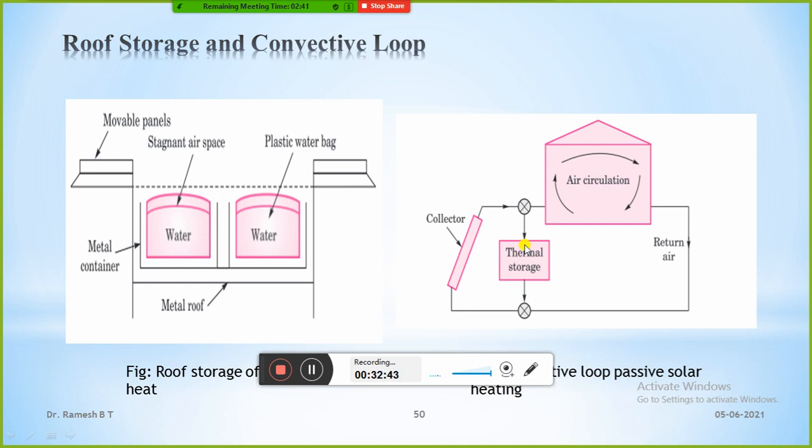If more solar heat is available than is required for space heating, the floor vent may be partly closed, and this heated air then flows through the bed, where it deposits heat, meaning where the air circulation is. Once the room air reaches the required heat, we stop this process, closing the vent, and the collector heat goes directly into the thermal storage made with a bed of rocks.